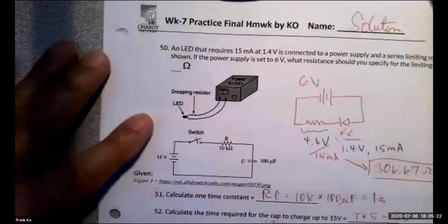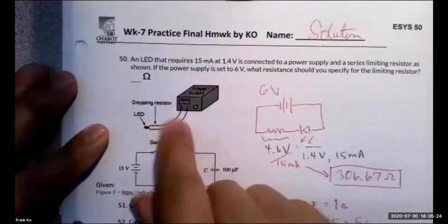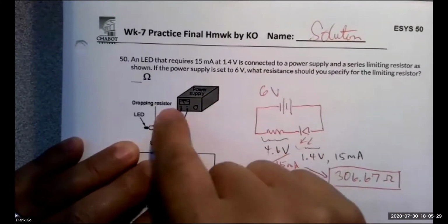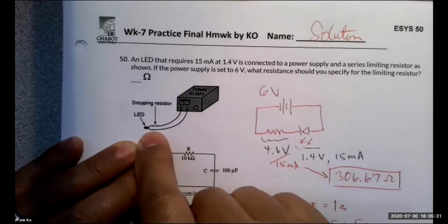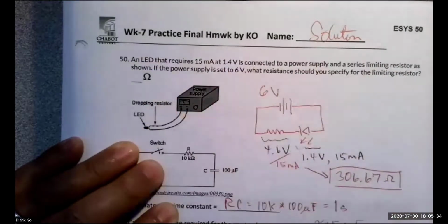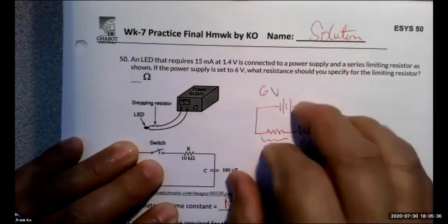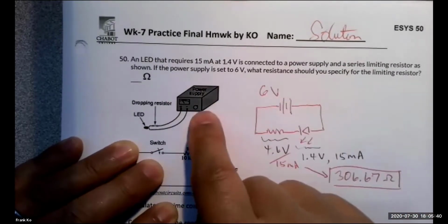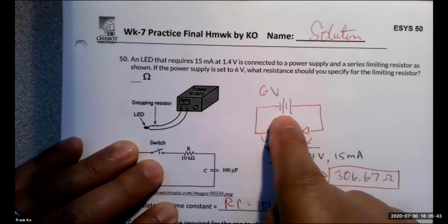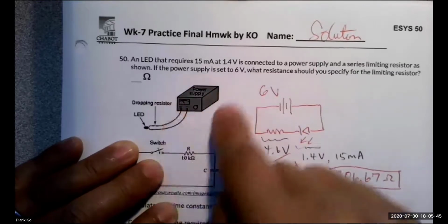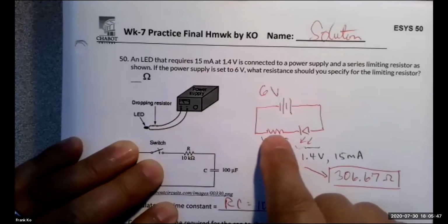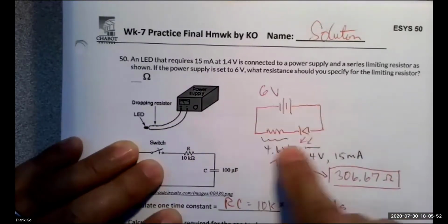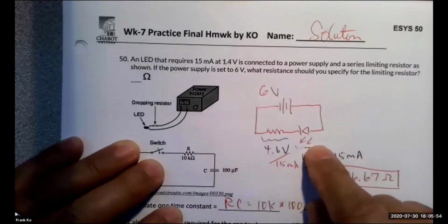So as we look at this particular exercise, we happen to have a circuit, power supply, LED, and a series resistor. The best way of reconciling any kind of a word exercise is to draw the schematic. So in your schematic, you see a power supply, you see a DC power voltage source here, yeah? In your schematic, in your drawing, you have a resistor and an LED. Now, keep in mind, the polarity of the LED is very specific.